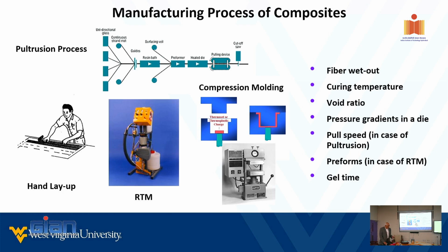Very good question. There are many limitations as well, but what I want to say is, I don't know how many of you know, the modulus is about 1/4 of steel. Like 28, 29, 30 MSI, million PSI is the steel modulus. This is about 5, 6, 7, so 1/6 of difference.